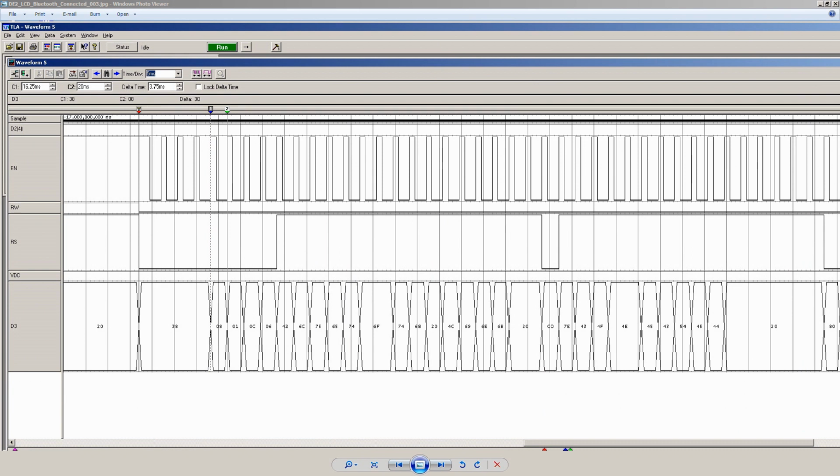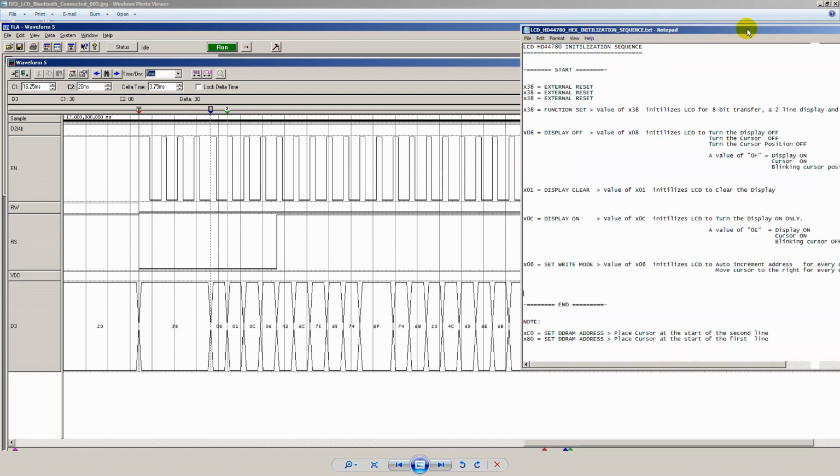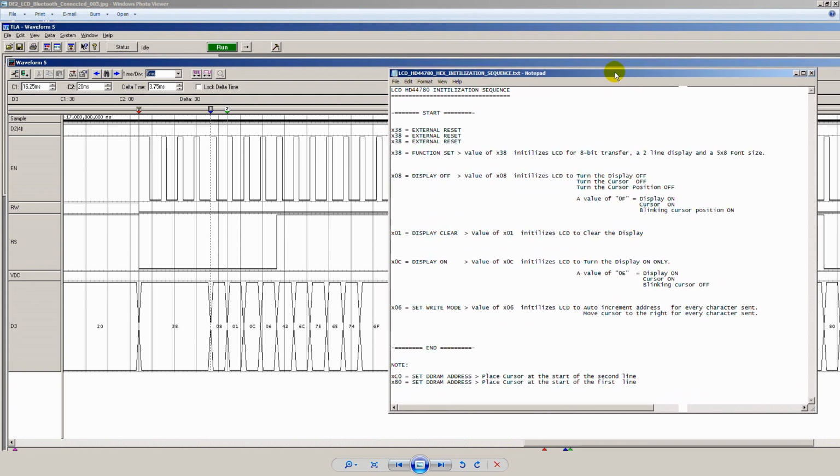And you'll get different display modules that interpret specific driving signals, and usually they're all laid out and described within the data sheet for that particular LCD display. So for this one, the HD44780, I'm going to talk about that and the initialization sequence for it. I'll bring in a set here which lays out how it all works in the hexadecimal values, and I'll talk also about the enable and the RS lines and how they function.